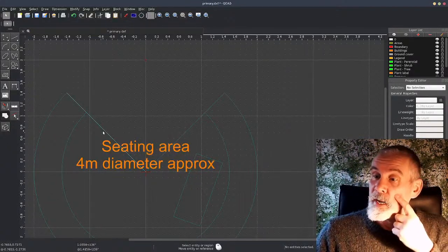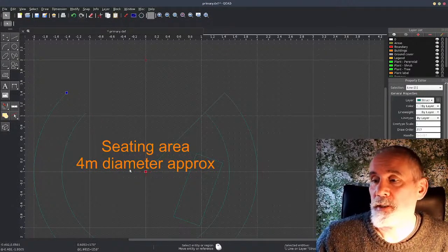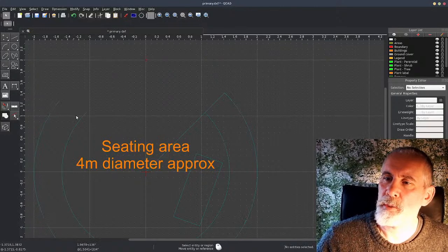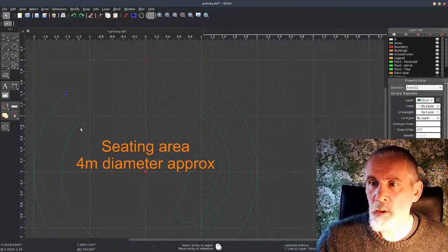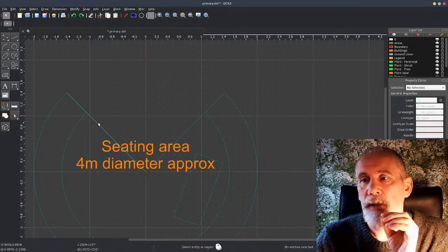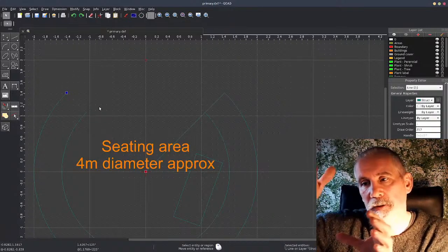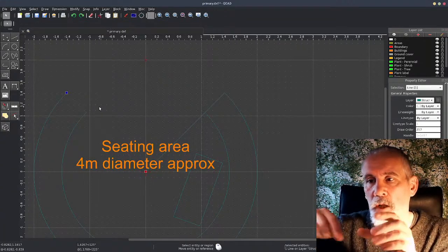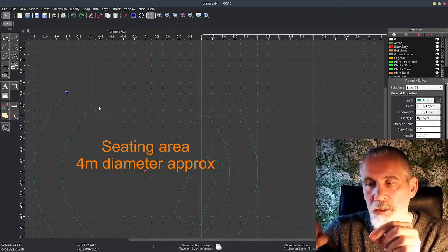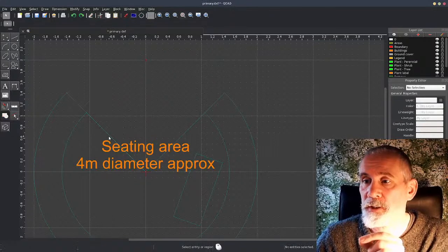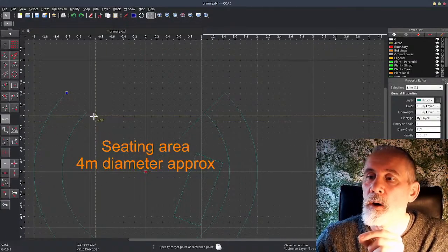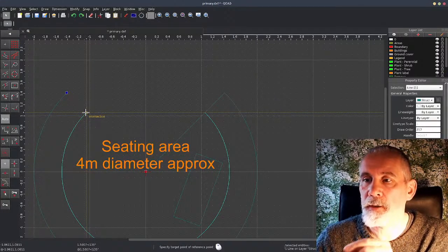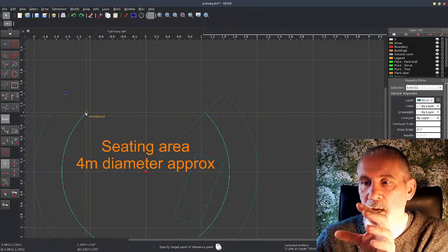And then another very handy hint, you're getting lots of handy hints today. Rather than just deleting that and then creating lines between the ends, which is what you can do, the great thing is that I want to create the end for the end of the gabion walls. So rather than deleting it and then drawing another line, you can just use the existing guideline and make it form part of that shape there.